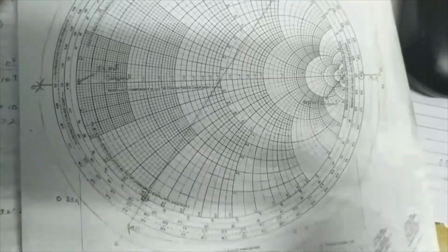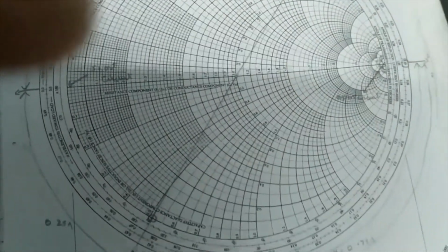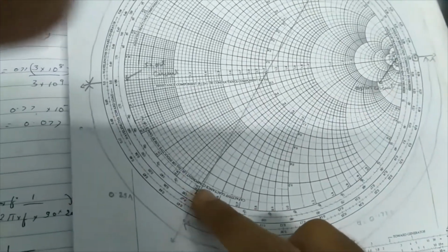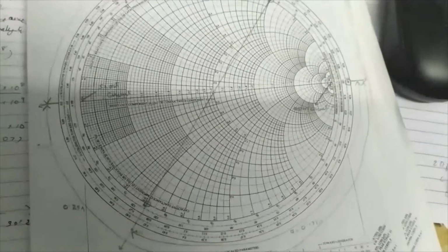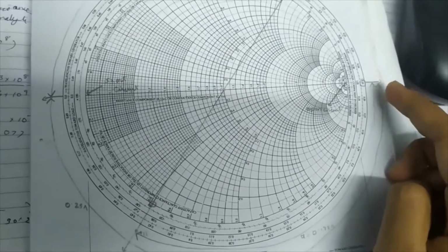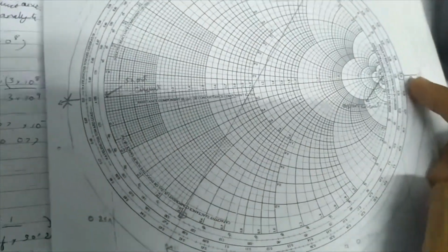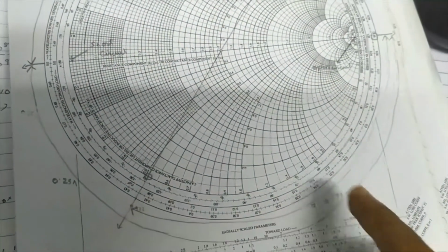meters. Next, mark the point 0.53 that we have got on the Smith Chart. Since it is a capacitor, it will be negative and it will be below. Since we have to convert the transmission line from open circuit, from here the angle is 0.25. From here we have to find the angular distance till here. If we subtract, the distance is 0.1 in terms of wavelength lambda.